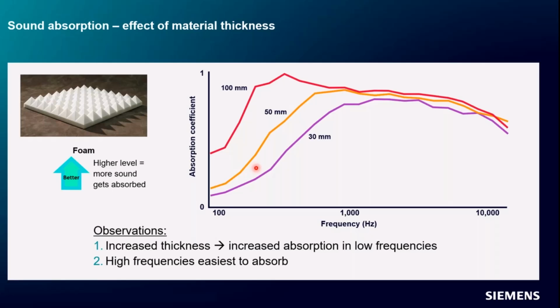And so the more material we have to absorb that sound, the better it's going to work at those longer wavelengths. And then you see we more than triple the original value all the way to 100 millimeters, and we get very drastic improvement at the low frequency. Helps everywhere a little bit, but really important to help our low frequency concern.